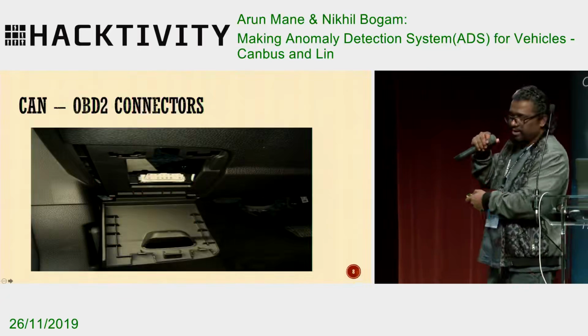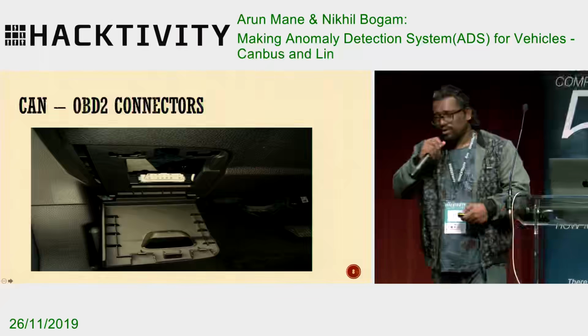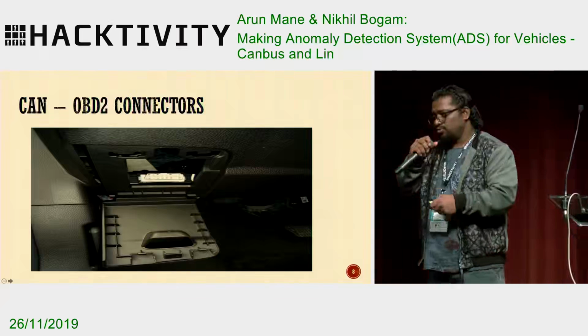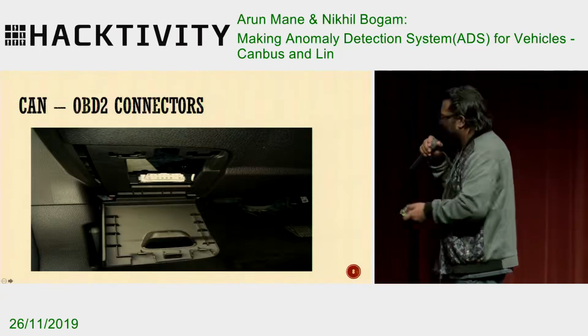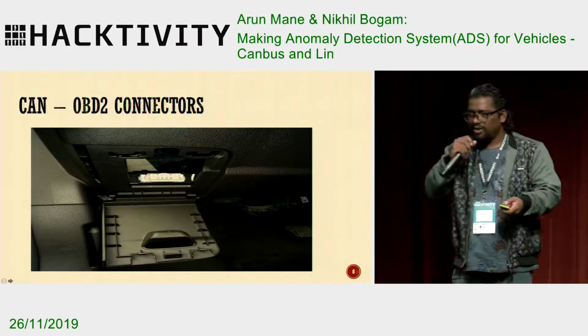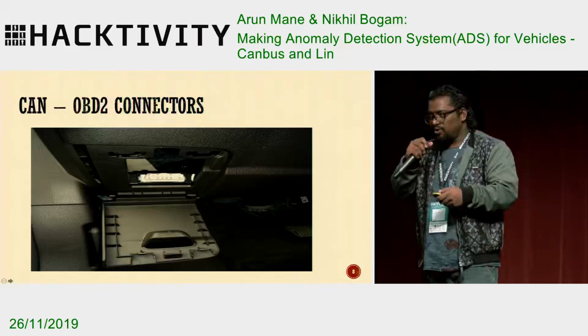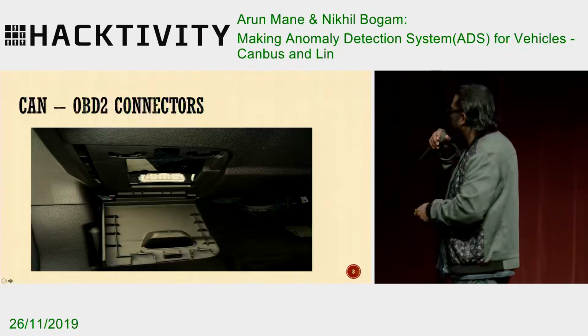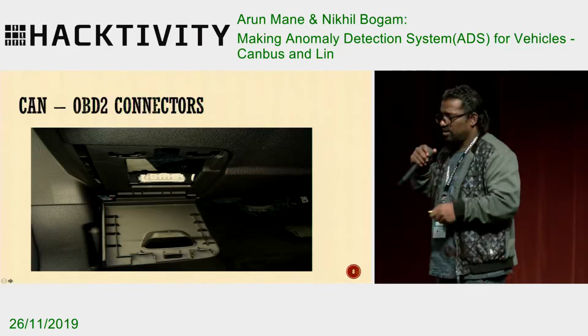These are the OBD2 connectors. You can use some sort of OBD2 to DB9 or OBD2 to USB connector, and you can connect. And if you have hardware devices which can talk on CAN bus, LIN protocol, and other UDS packets, you can directly communicate with the cars, and you can sniff communication.